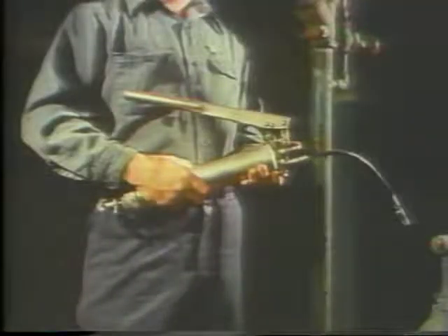Grease is usually applied to a bearing by using a grease gun. Grease is injected into the bearing through a grease fitting on the bearing housing. A grease fitting is a small rounded projection from the housing that has a hole through it. The fitting on the grease gun must match the fitting on the housing. To grease a bearing which has a fitting, it is often necessary to remove a drain plug from the housing before any grease is added. The plug is removed so that old grease or excess grease can drain out.